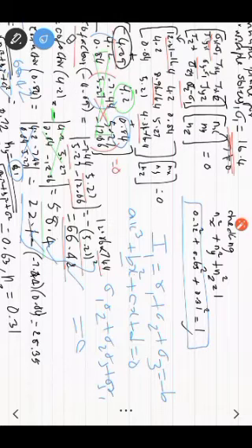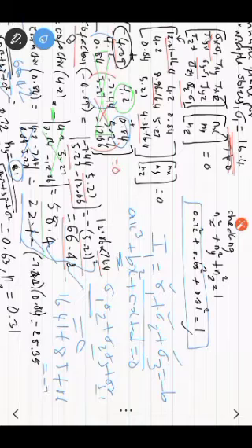So if you know the values, you just multiply this, and if you want to check whether sigma 1, sigma 2 and sigma 3 obtained by using the equation, using the calculator, are right or not, you just add them and see whether it is equal to minus 25.41. What you have got is 16.41 plus 8.5 plus 0.6. You add it up, this is near to 25.61. So you have to put minus b, then only you can equate it to 25. This is how you can check this, and for the angle you can check using this value.